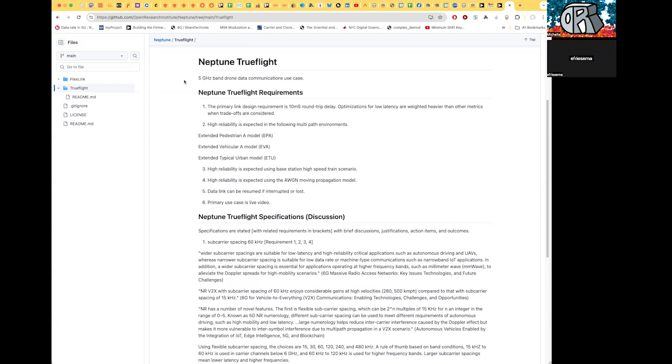And that requirement is important to us, and has a lot of repercussions in the implementation. And then six, just to establish that the primary use case is live video and not necessarily the control link. The control link in most drones is a separate radio. So what we're focusing on is the data link that delivers data, live video with possibly some telemetry.